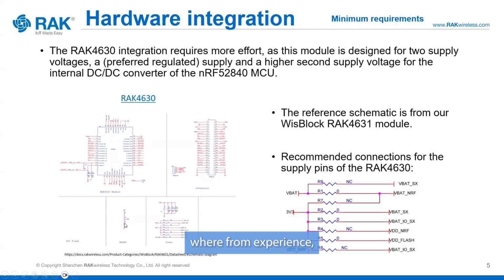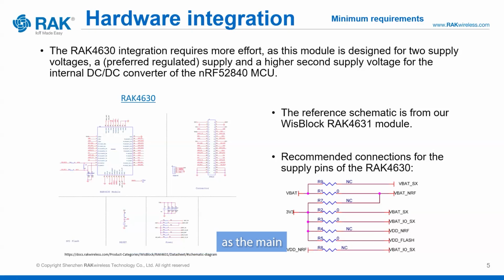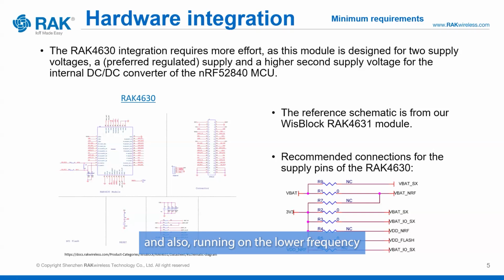From experience, most customers that buy a RAK4630 or a RAK11720 are using this module as the main microcontroller in their system. It is more the RAK3172, which has limited memory capabilities and also runs at a lower frequency, that is used as a plain modem.